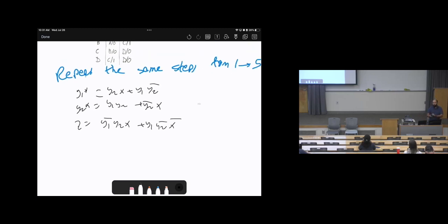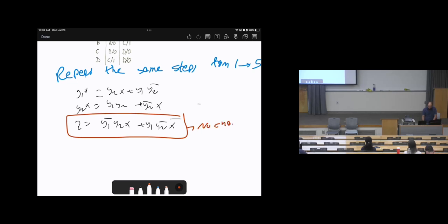So we already know how to deal with this. When we discussed the D flip-flop, we used to say this is D, this is D. That's fine, that was in the past. Now we need to use JK flip-flops, not D. Remember, for Z there is no flip-flop, so Z will remain as is. No change on Z because there is no flip-flop. What we are worrying about is Y1 star and Y2 star. How can we achieve this?